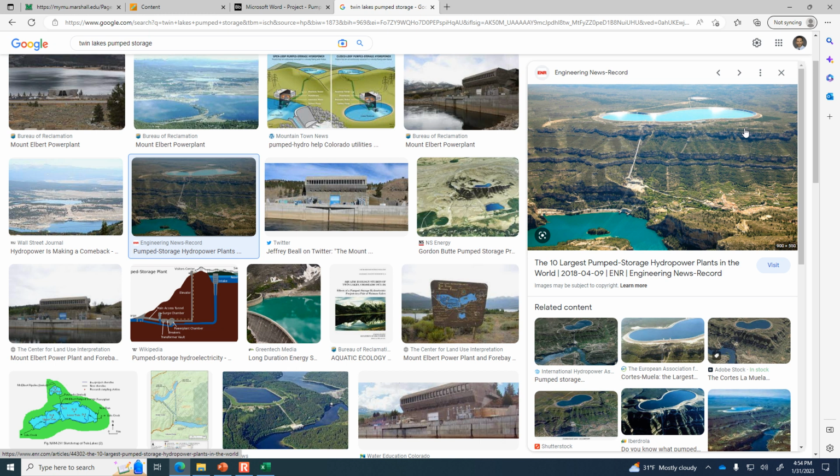Yeah, if you're using it for water supply, I don't know why you would send it down for electric and send it back up. The water that I drink doesn't come straight from a pump at the Ohio River to my house. It goes to a storage tank. They lift it to the storage tank and then they can switch off the pump. At night, that elevated tank provides pressure to the house and a pump doesn't have to constantly be running. So there's economic value in having it in that elevated tank, simply so that you're not having to run any equipment continually.